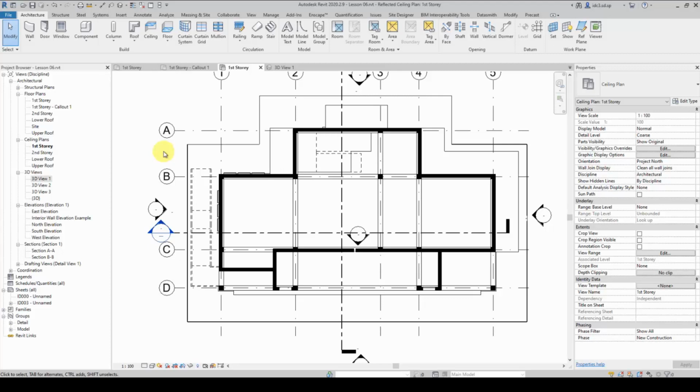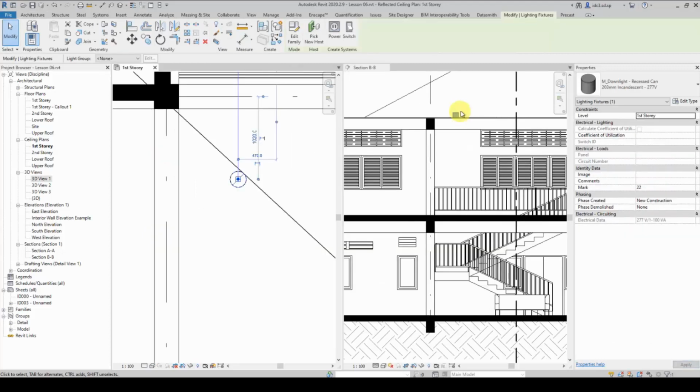When I click on sketch ceiling, I will be in the draw mode, so it will allow us to draw a couple of components down here. Later you will learn in the instructional about auto ceiling, but I'm going to just use this one first to sketch a rough ceiling. I just want something quick and dirty so that I have a ceiling to work off from now.